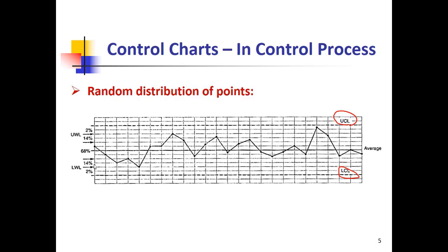Like you can see, maybe 2 data points are close to the limits. The majority of the data are close to the center line, within one standard deviation, and maybe a few data are located within 1 or 2 standard deviations. Like here, we have 3-4 data, and here we have 4-5 data. My lines are not accurate, but as you can see, the majority of data are really close to the center line.